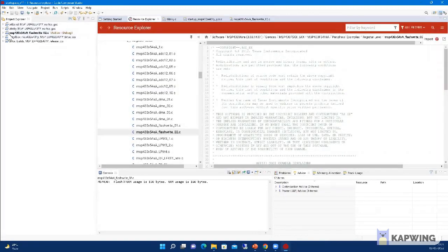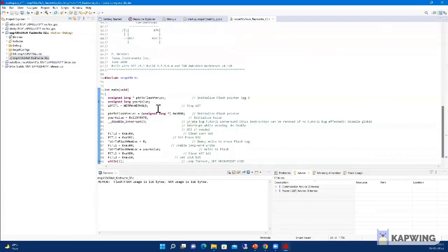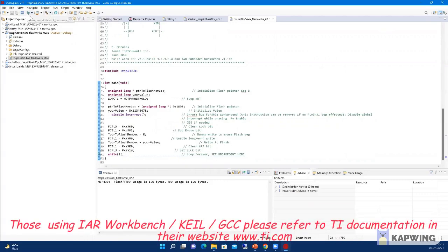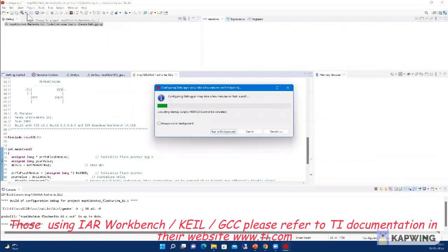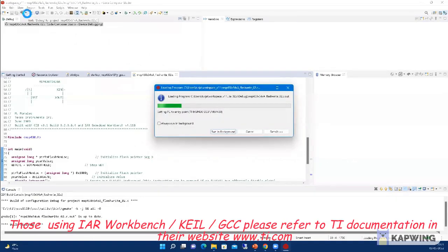Now coming back to the actual code, that is this one. I have just modified it in this way, maybe modifying the values a bit and tweaking them. I have an MSP430 hardware connected with me. After you design your code and make whatever changes you want, you simply click on debug, or you can directly download your code if it is already compiled. Once you download your code, as you can see, it is being downloaded. You can simply run the code and we can see that the actual data is being stored inside the MCU. So we'll wait for the program to be downloaded.